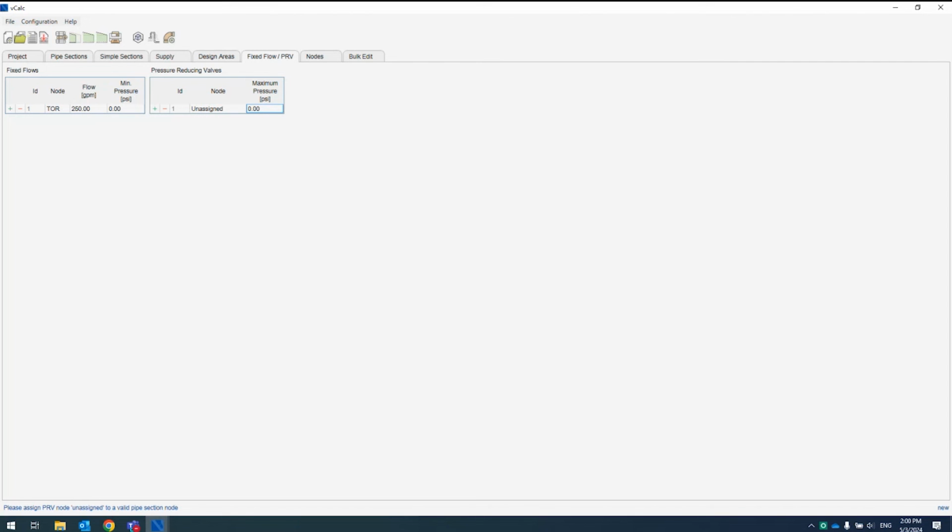If you want a more in-depth explanation, we can go into that. I think it's covered in the customer learning portal as well. But basically, if we see a pressure exceeding this maximum pressure at that node, all downstream nodes will see the limited pressure. I know that's a very short explanation, but you could reach out if you'd like something a little bit more specific about that.